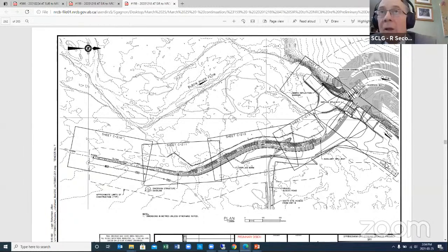So if we look at figure 19, at an elevation of 1217 at the gates, that would mean that water would be pushed into the auxiliary spillway. Would that be correct? Or would it be overtopping the auxiliary spillway? That's right. And where does that water go? Once it overtops the spillway, it flows through the historic Elbow River channel floodplain and back to the primary channel. Okay.